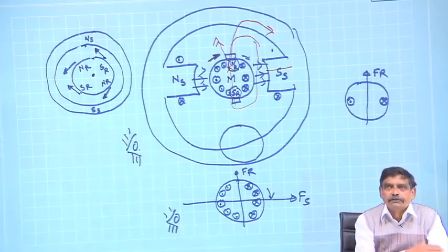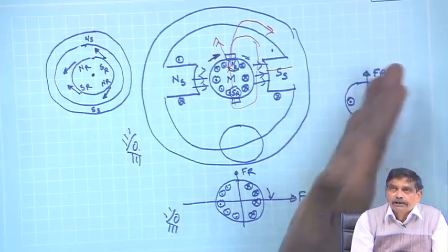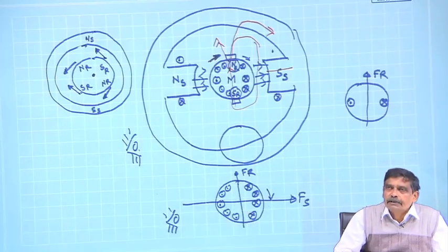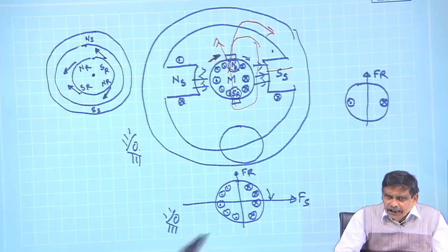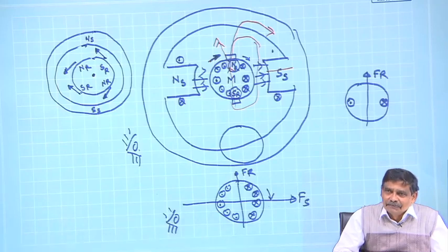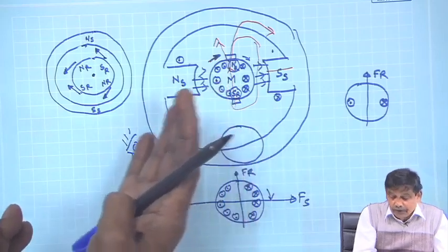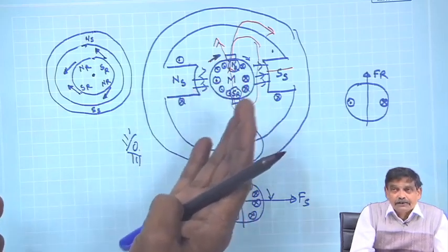It never goes this way and that way as it would do like this. So, that thing is taken care of by commutator segments and brushes. Here we see that conductors are rotating, but the field is stationary, and it must be stationary because a DC motor, we know, produces a steady electromagnetic torque.